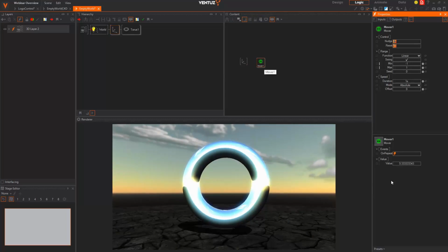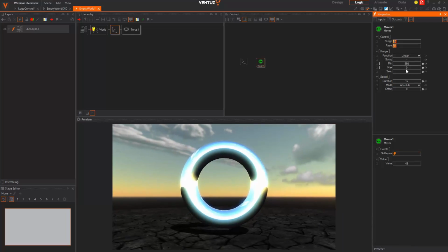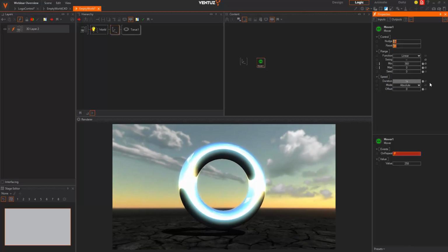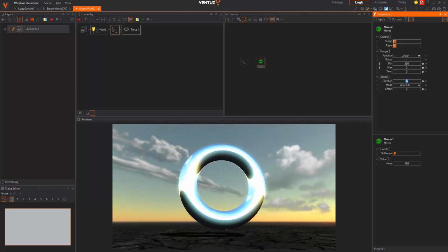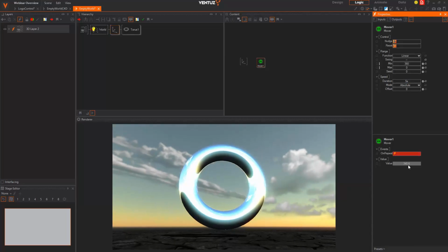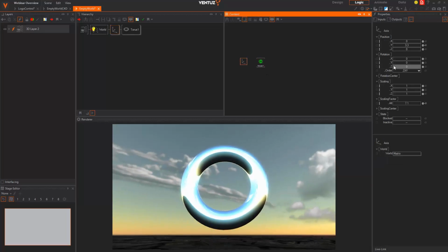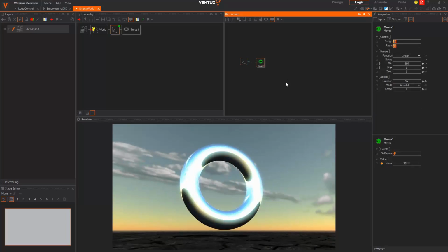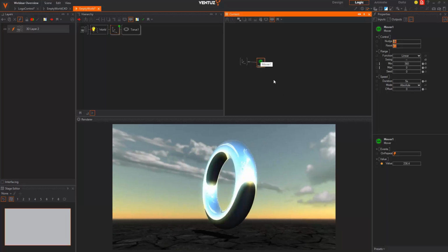We can just use a preset that is using a rotation, generating values between 0 and 360, so that it will just generate values between those two limits in the given duration, which you can change to 5, and now in the time of 5 it will count down from 360 to 0. And we can just apply this to our y rotation by dragging and dropping the property name of the axis onto the node that we want it to be connected to. And this is basically it, what you need to do to build your logics.